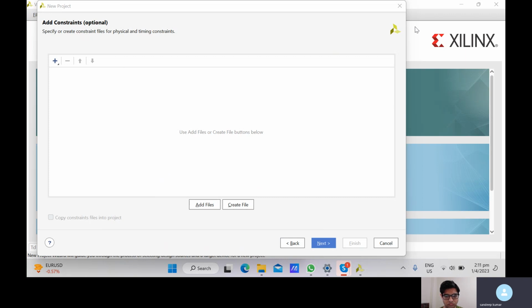You can create that hardware on the FPGA. Let's say I design the same multiplier so it can run at 500 megahertz, but you design the same hardware and maybe it cannot achieve 500 megahertz. So even if the clock is 500 megahertz, until your hardware achieves that frequency, it will not work. It will misbehave and give you incorrect results.